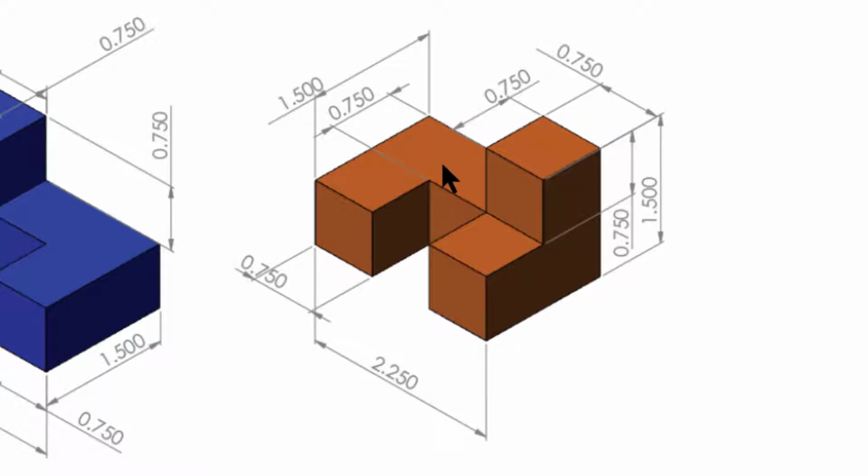I'm going to start by sketching out this rectangle that is in the back of the block. That rectangle will be 0.75 tall by 2.25. I'll extrude it to 0.75 deep. Add my two front nubs, just like the blue one. Add my top nub. 3 extrusions total.